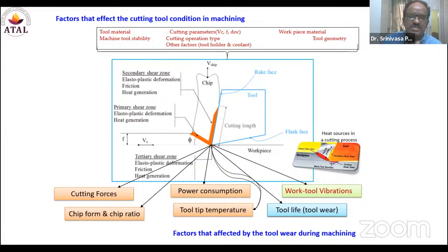Definitely. See, while giving input instructions, you may not consider all the factors, but these are the factors. It can be forces, temperatures, deflections, tool wear, whatever they may be, they will be available as output process variables. In an open loop machining system, these factors are ignored. They will not worry about these particular outputs or variables. Their intention is to execute the task and produce the part.